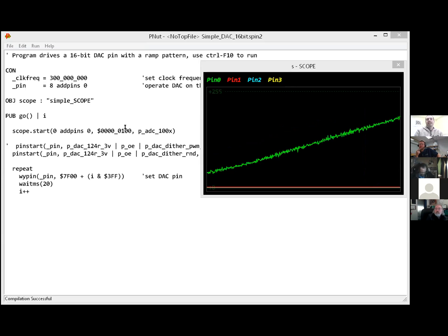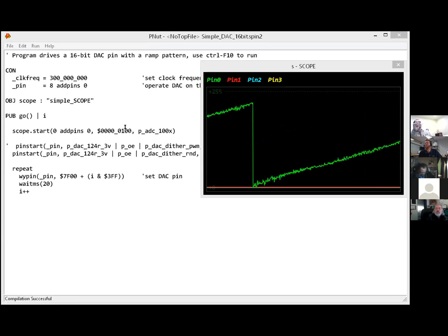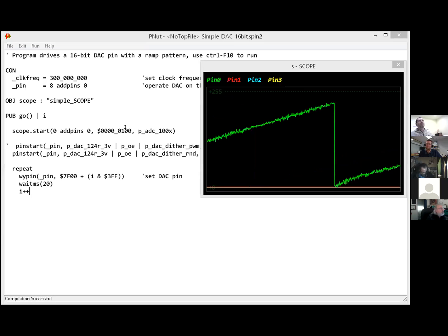Because it's an 8-bit DAC and it's toggling 1 LSB. So that dither noise is way down there, and it's at a very high frequency. It's at the clock frequency divided by 256. So for practical purposes, if you're using this for like an analog DAC for audio output, that is just going to be filtered out in the signal chain, and you're never going to notice that slight noise pattern. You'll never notice it.